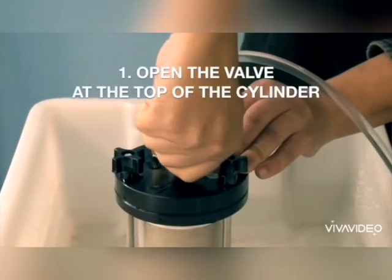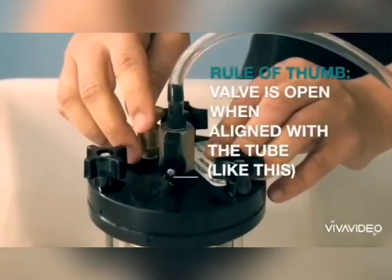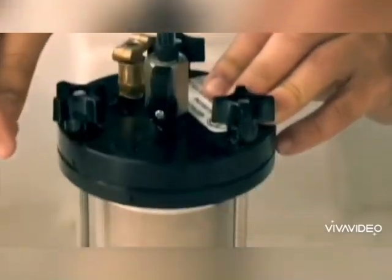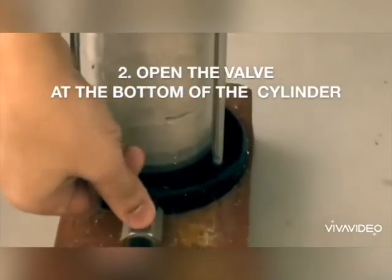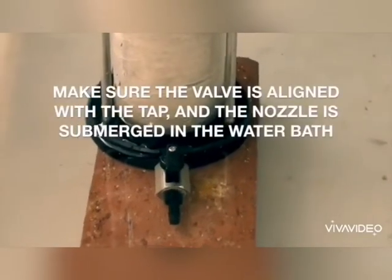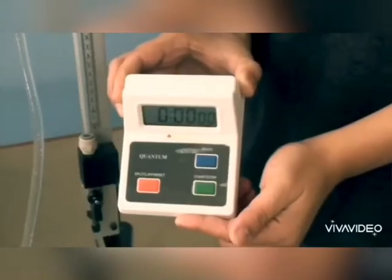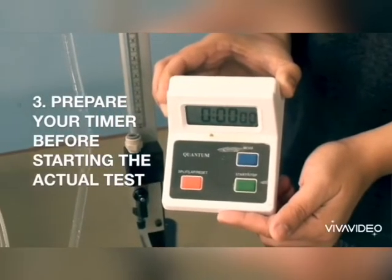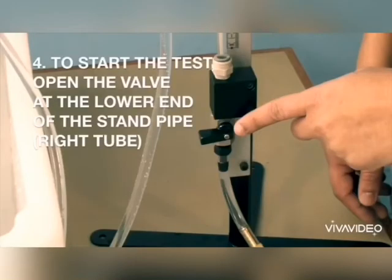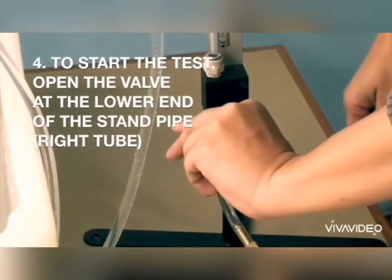First, open the valve at the top of the cylinder. Rule of thumb: the valve is open when aligned with the tube, like this. Second, open the valve at the bottom of the cylinder. Make sure the valve is aligned with the tap and the nozzle is submerged in the water bath. Third, prepare your timer before starting the actual test. To start the test, open the valve at the lower end of the standpipe, which is the right tube.